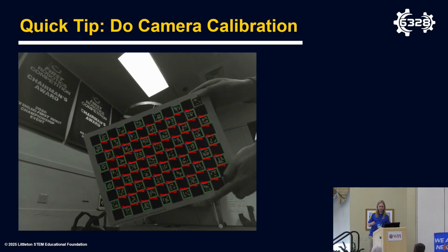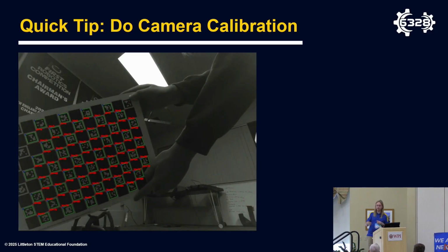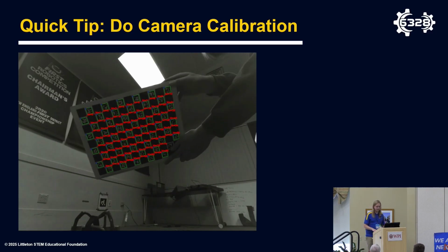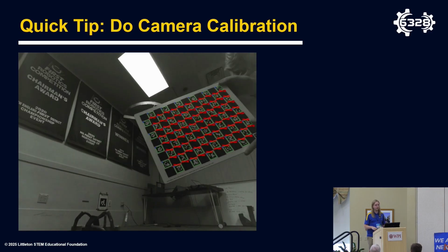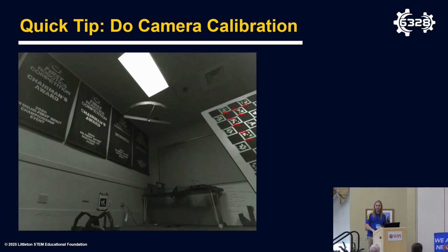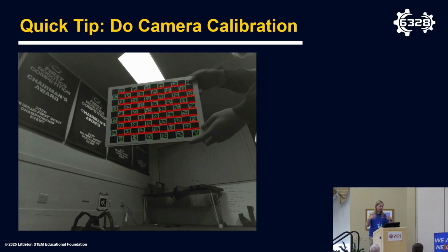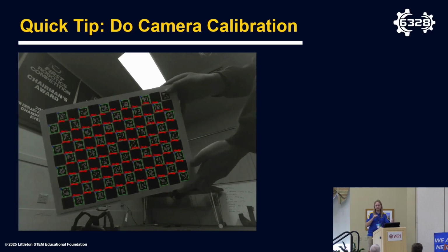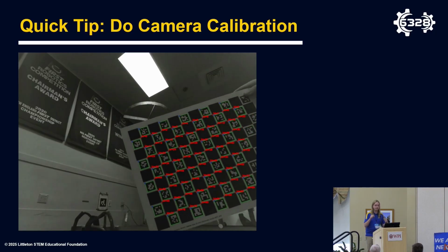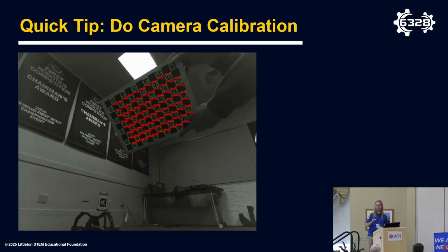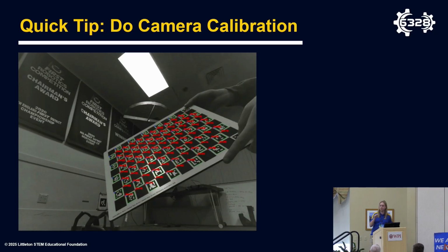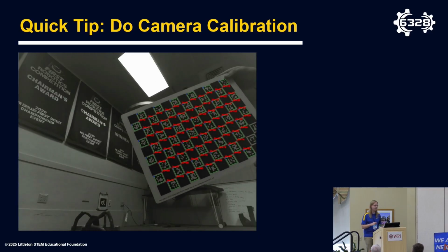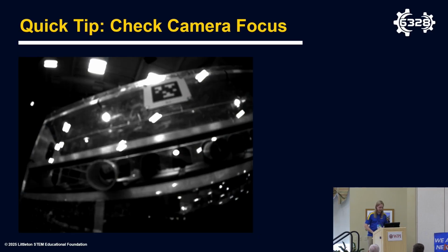The reason for that is that most cameras are really just not built for machine vision, so most of them don't support that. Sort of an interesting anecdote is there was a time in 2023 where we had 4 cameras on our robot, all identical. We mixed up the calibrations at one point. We were able to figure out which one corresponded to which camera by simply testing them out and seeing which ones were good and which ones were bad in terms of the quality of the pose estimates. It was really dramatic in terms of what difference it made swapping out those calibrations.